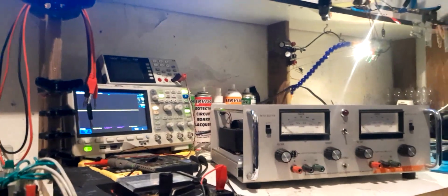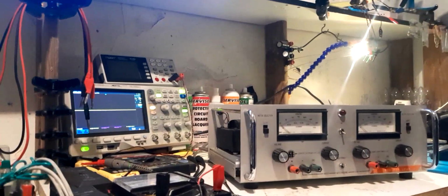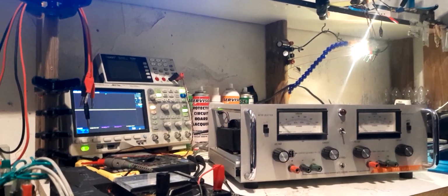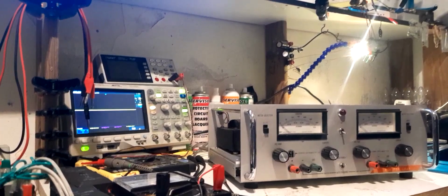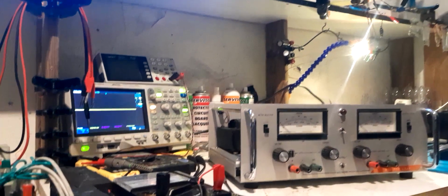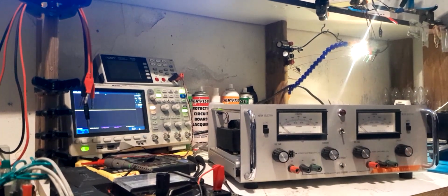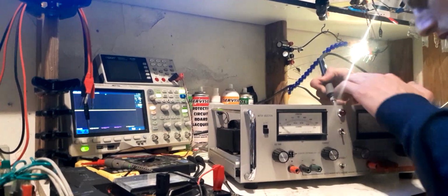Even the areas where the board is good and it's not burnt at all, the traces still lift really, really easily. The old boards were constructed differently to the way we construct boards now. The glue was different, and it gets old, and it just doesn't hold the traces down when you get it hot. So I'd rather try and leave the bottom side of the board alone as much as possible for that reason.